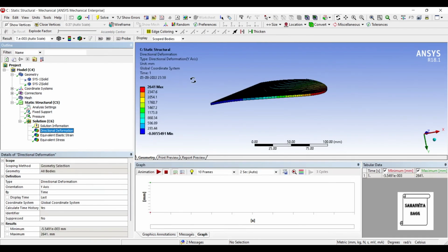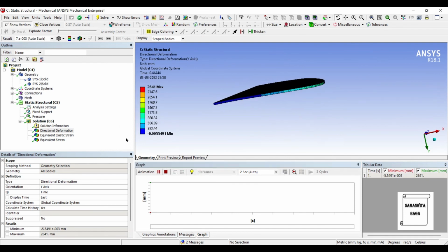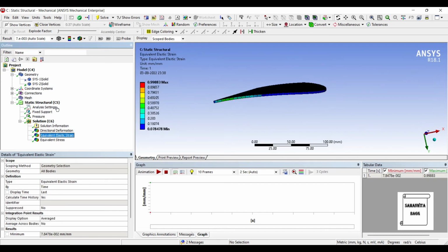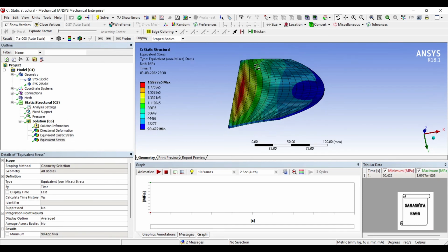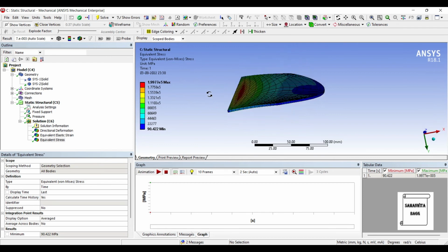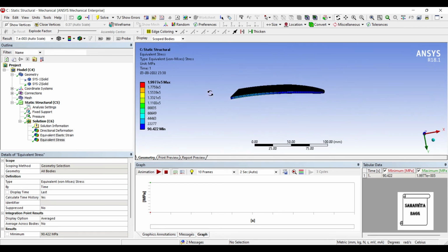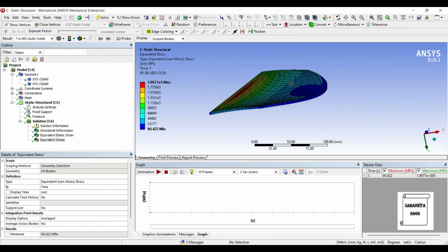So you can look here. Now the dimension that we have given is too thin, hence it is showing a little more deformation over the body. But you can give it a little more thickness, so it would be better. And you can see here the maximum stress is generated at this zone. The zone is still free from the stress. Hence, my design would be an optimum design because I am using lesser material as compared to the initial way